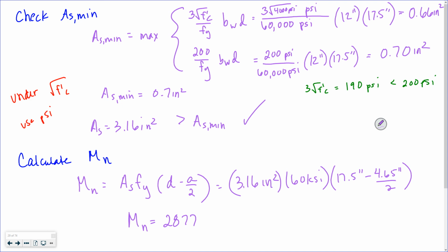So my nominal capacity, hold on, I'll let you guys verify that. Okay. What are the units? Right? I've got inches squared times kips per inches squared times inches, so kip-inches.